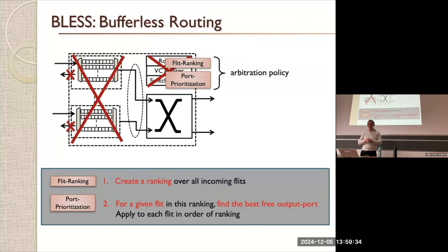The paper also discusses a case where you still have header information and source and destination information only in the first header packet, essentially. But then you run into two worms hitting each other, and at some point you may need to break a worm. That's not an easy thing to tackle. So for complexity reasons, we discussed that case and we say you can do it, but it's much more complex than treating each flit as a packet.